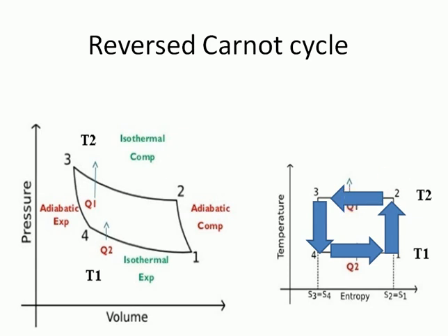That means in this case, I must pump the heat from the atmospheric temperature, 0 degrees Celsius, to the room which is to be maintained at 20 degrees Celsius. So in Jammu and Kashmir the same cycle is used as a heat pump, while in Solapur the same cycle is used as a refrigeration system. This is the difference between refrigerator and heat pump.